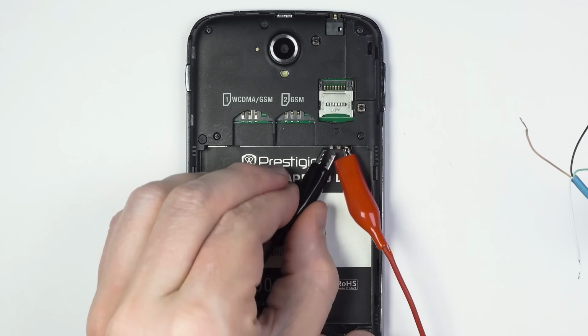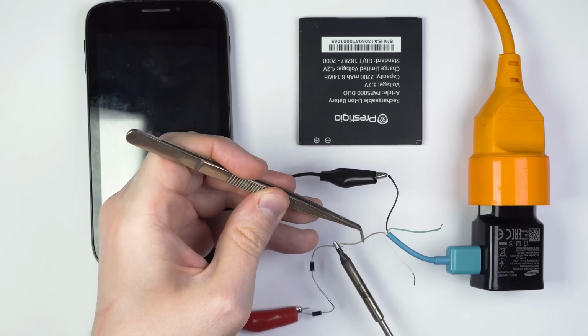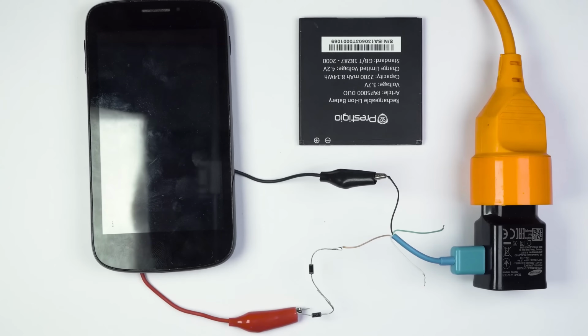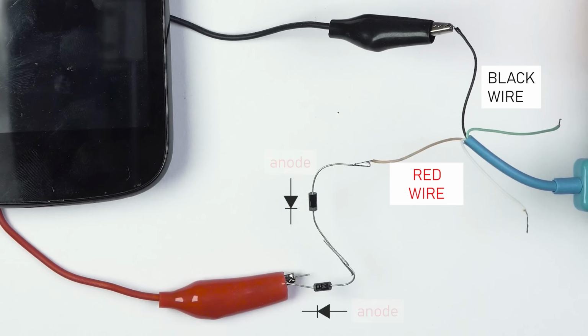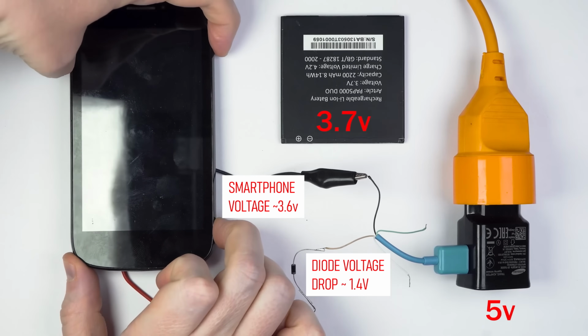Let's say you have an old mobile phone that needs to be powered from a USB power supply without using a battery. The nominal voltage of a lithium-ion battery is approximately 3.7 volts, while the USB supply outputs 5 volts. If we take two diodes and connect them in series, the anode, of course, must be connected to the positive rail, that is, the red USB wire, we will get a voltage drop of about 1.4 volts,